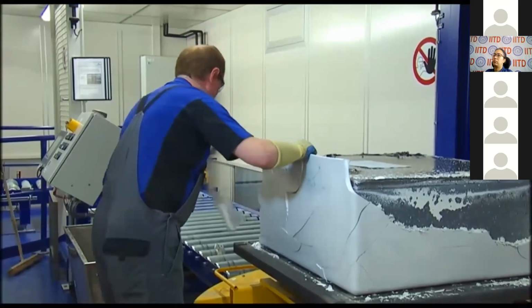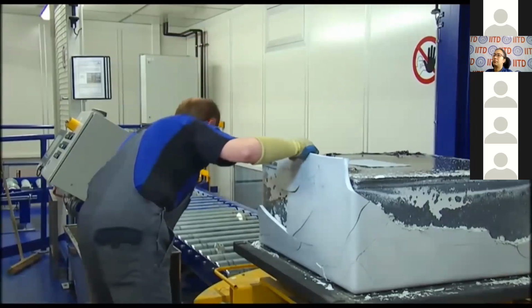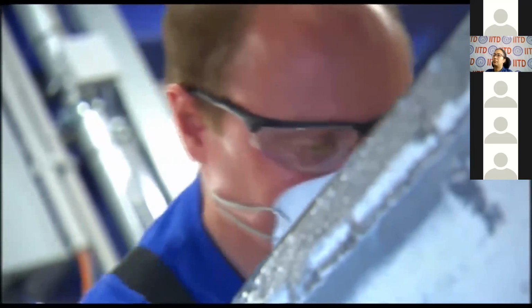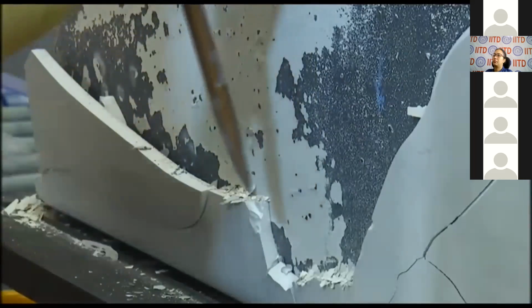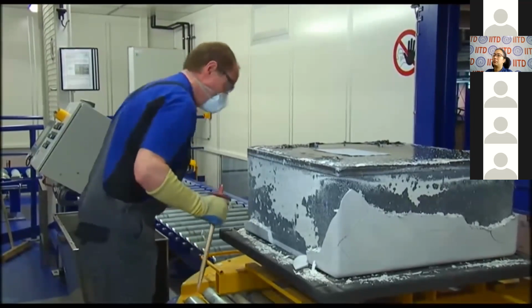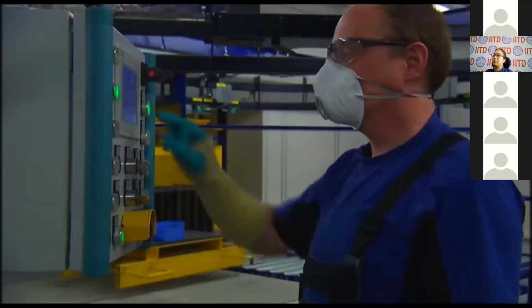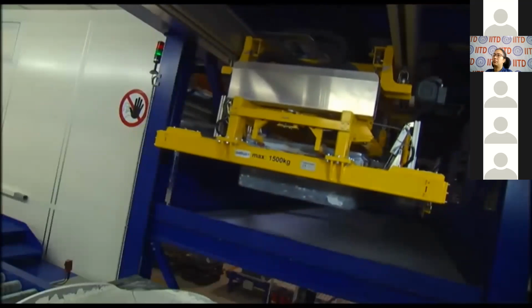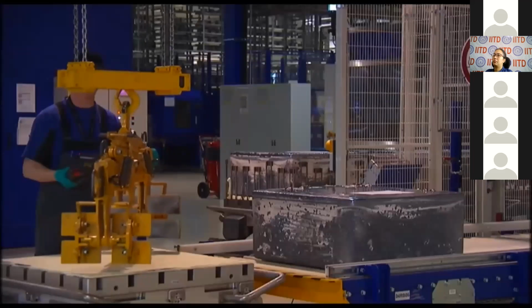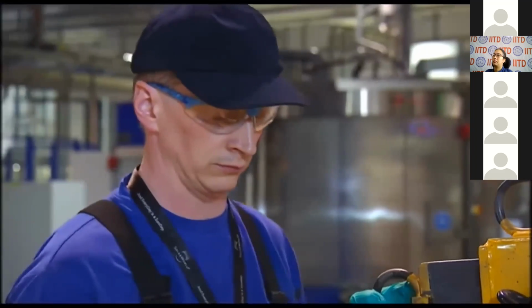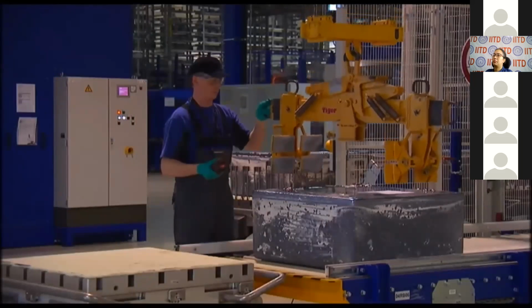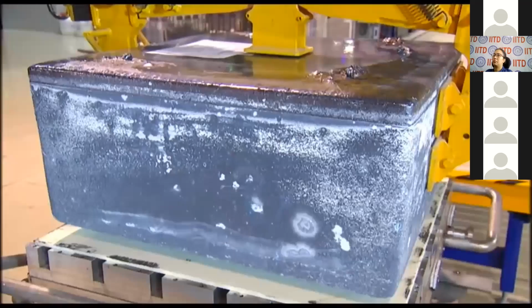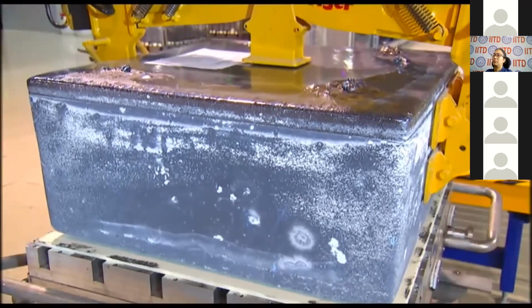After 3 days, we have produced a multicrystalline silicon ingot measuring 84 by 84 centimeters. The efficiency of the subsequent solar cells depends entirely on the quality of both the melt and the crystal structure. Upon removal from the mold, the silicon ingot is transported from the crystallization center to the ingot store. While continuing to cool, it remains in an intermediate buffer zone, awaiting further processing.